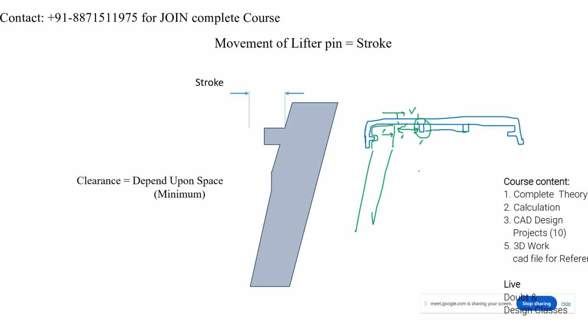Okay, so basically there is a limit for the clearance, and there is a limit for designing the lifter pin also. But for the external feature, is there a limit or not? No, there is no limit. However, we should take the minimum clearance. We can take 2 to 3 or a maximum of 5 mm clearance. We cannot take a clearance of 15 mm to 20 mm, because there is no requirement for that. Correct. We have no requirement for 15 or 20, but we should take the minimum distance there.